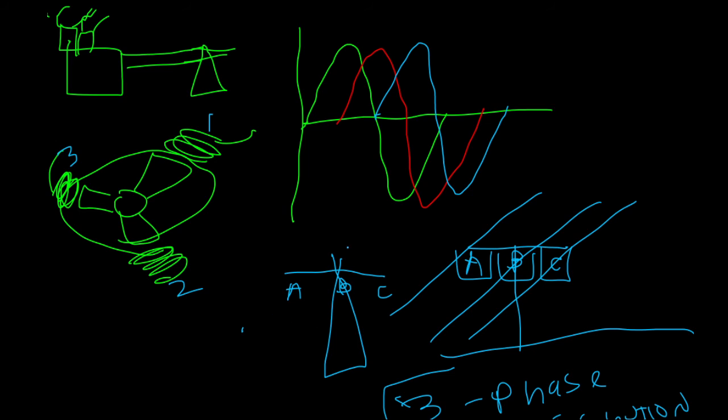And so sometimes you'll see lines that have like 6 things on them, or a tower that's got 6 things. What that actually is, is 2 circuits. It's 2 sets of 3-phase distribution. So it's ABC and then CBA, just sort of stacked on top of each other, but what that functionally maps to is two different turbines in the power production facility. And so that's why you'll see coming out of a power plant, like 5 or 6 towers, each with 2 phases, because they have a lot of different turbines. They're not just turning one turbine, in some cases they're turning dozens of them.